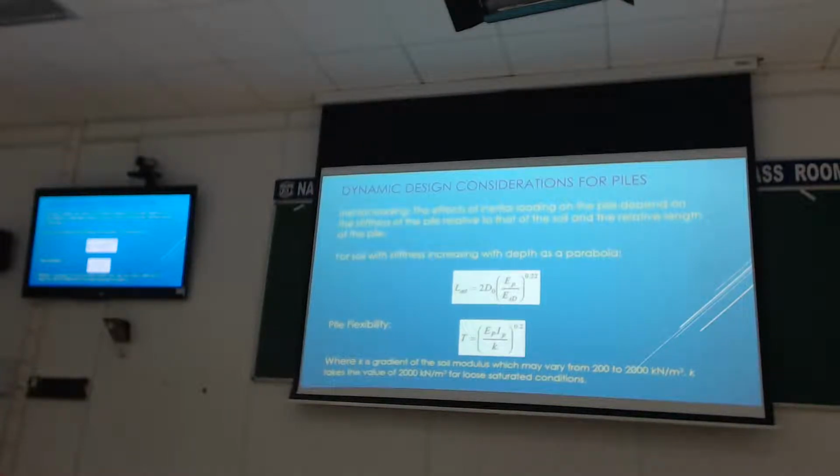This is a very structural engineering approach to soil mechanics: give us one number, and the one number will be K, because it's a spring constant. The soil modulus normally people take is in the range of 200 to 2000 kilonewtons per cubic meter. If you have a range like that, you will pretty much get the answer you want by choosing the K properly, I should say. But forget calculating that, you can see where the concept is.